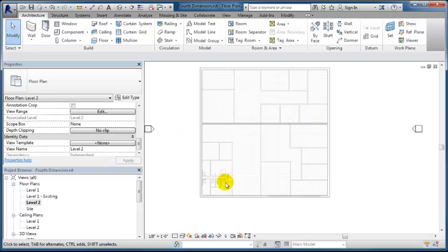And what I want to do is I want to have floor trusses spanning from here to here, and then spanning this distance from here to here. And then on top of the floor trusses, we will put a metal deck and concrete floor system. And then we will create a roof system and actually have it slope towards this center wall, so that there could be roof drains in this floor system. We'll also add some columns in this wall to help support the floor framing and roof structure.